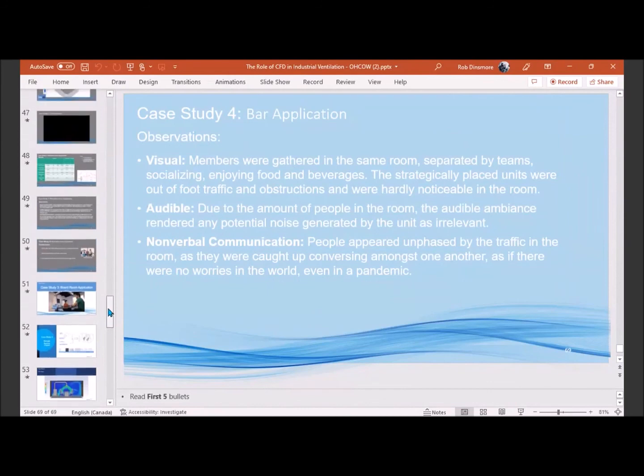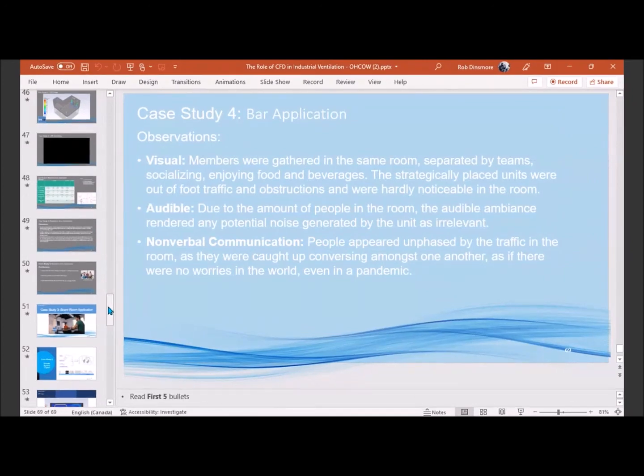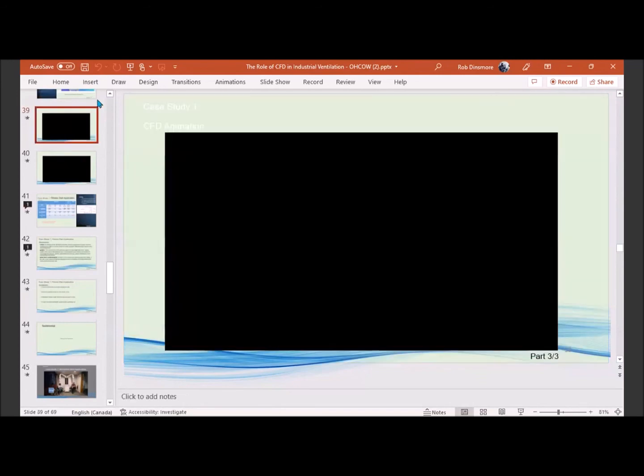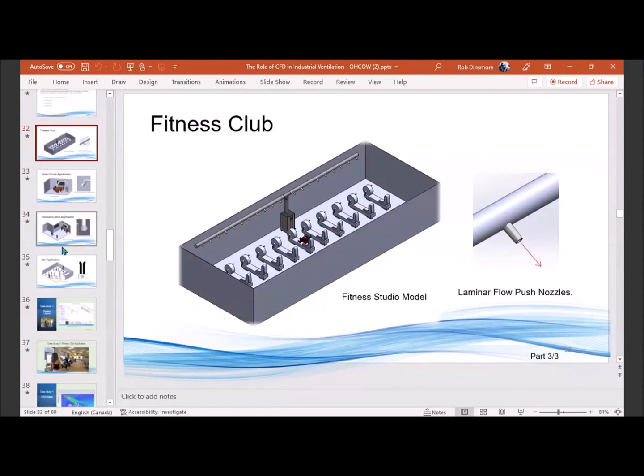So there's a question about the idea of mitigating near field effects. In quite a few super spreader events, it's been mentioned that the fans are blowing on the people, specifically in the fitness center, on the exercise bikes, who are exhaling hard and blowing their infected aerosols onto others in the room. So he understands the ventilation reduced the concentration of particles in the room, but what about mitigating the near field effects of the people themselves? You're introducing fresh air, but then you're blowing maybe dirty air.